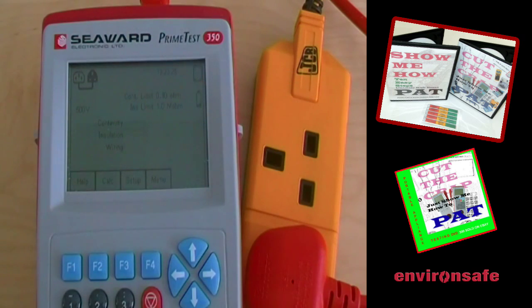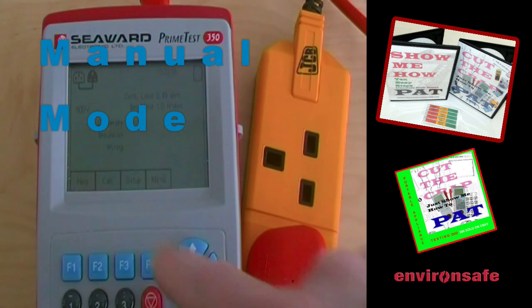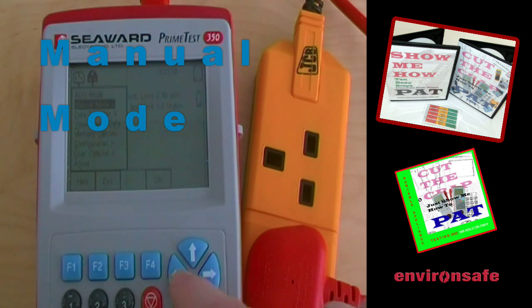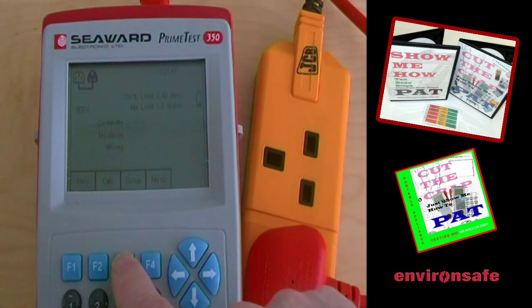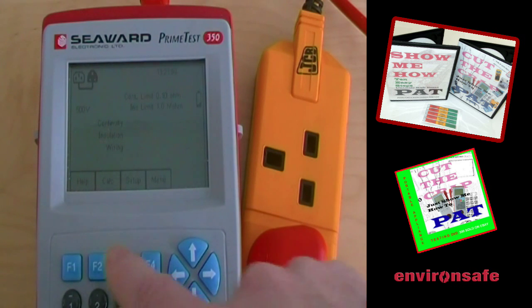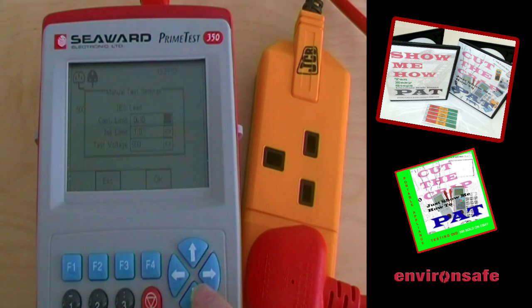Testing a 2-meter lead using manual mode. Press F4 to access the menu. Scroll down for manual mode. Press F4 to OK. Scroll down the menu. Select IEC lead. Press F4 for OK. Press F3 for setup, and the choices that you have here are continuity limits, the insulation limits, and the test voltage. OK that.